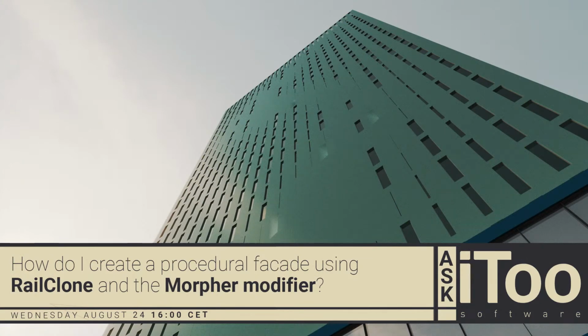This is a technique that I think people who have been around Max know about and have been familiar with for a while, using the Morpher modifier to create parametric facades. But to keep things really parametric, you can do this in combination with RailClone. I've had a few questions on the forum the last month with people using this technique to combine two RailClone objects via a Morpher modifier to create these kinds of parametric facades.